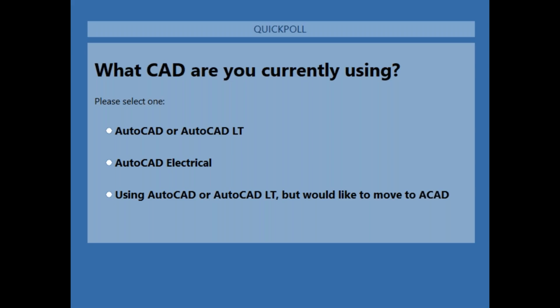At this point, AutoCAD Electrical has not been programmed or is not smart enough to look in the Vault for the catalog. However, there is a way to store your catalogs in the Vault for control, and just point electrical to look in the user's local workspaces. Or some companies just throw them out on a network share. But I like the idea of vaulting them so you can keep track of who's changing it and when they're changing it. Yeah, with the catalog database, that does become a little bit difficult, because then it tries to lock the files, because the Vault wants to lock them, and that causes some permission problems.